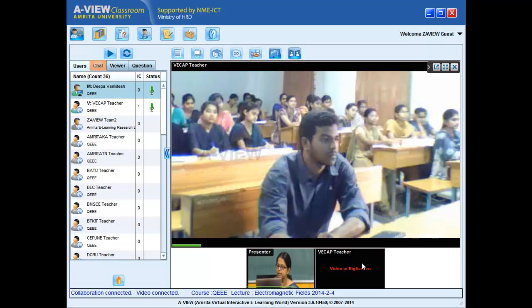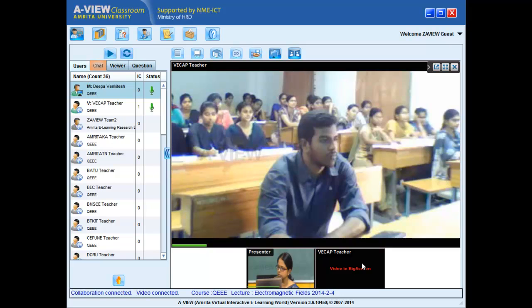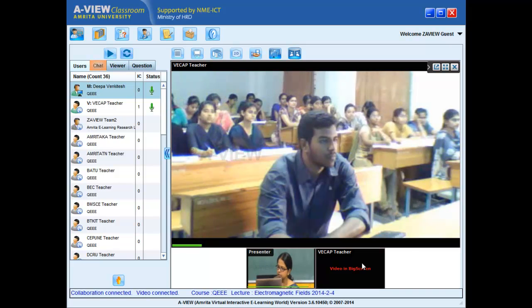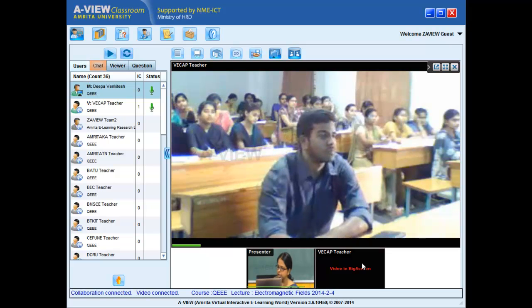This is the time dependent part, and you have the angular frequency omega. Just to remind you, e power j omega t is Euler's relation, cos omega t plus j sin omega t. So the real part of e power j omega t is simply cos omega t.